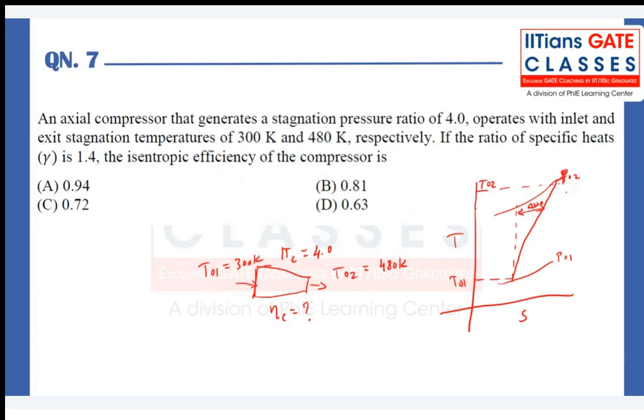So now, we know the pressure curves in a TS diagram are diverging. So if I trace back this constant pressure line on a TS diagram, I can extend it on both sides. Now if I see where the pressure curve exactly intersects the constant entropy line, where I have S1 at the start of the process, at state 1.